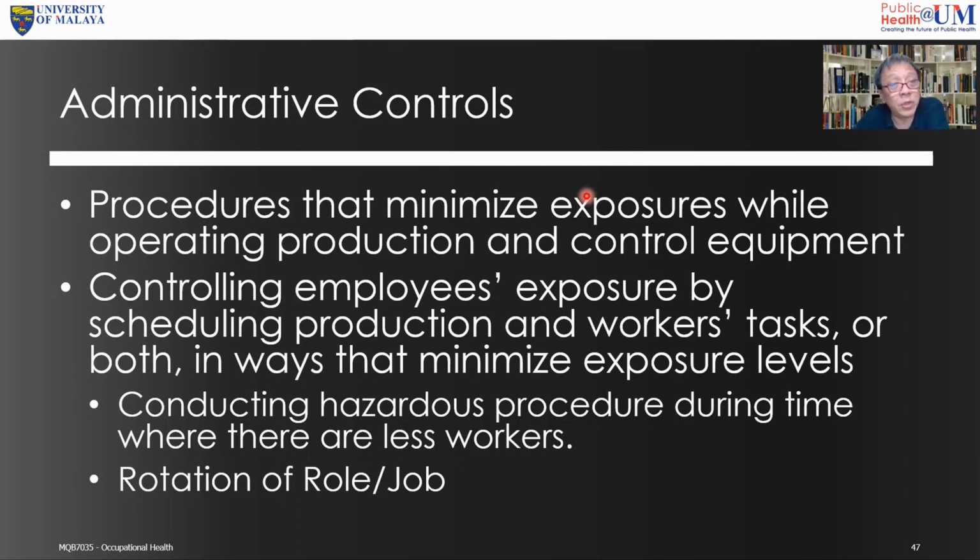That means you don't have to open up the machine, and you don't have to destroy the machine, or the equipment, or, let's say, the bar. So it's called non-destructive testing. To do that, sometimes you use X-ray. So to do X-ray, basically you need to ensure that there are fewer people there. If you see all the columns in the middle of the road for the MRT line, for the LRT line, or for your car, all those columns basically undergo non-destructive testing to ensure that there's no fracture within those columns before they allow the other process to continue.